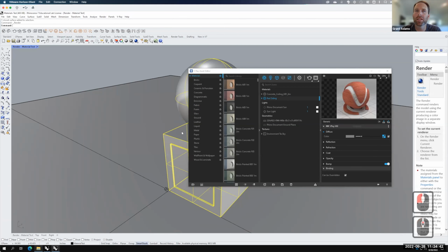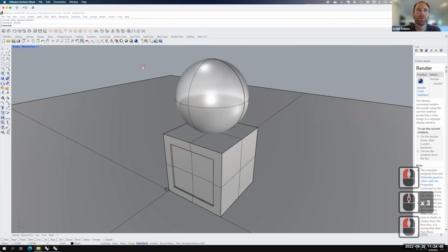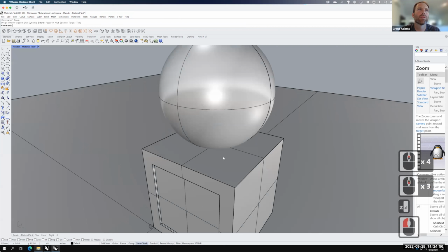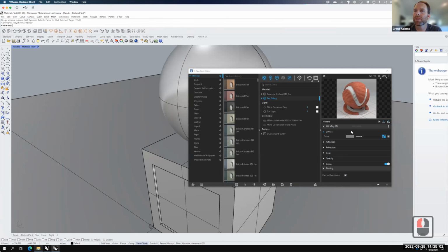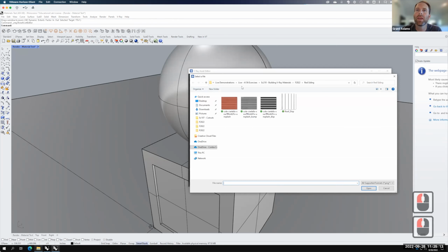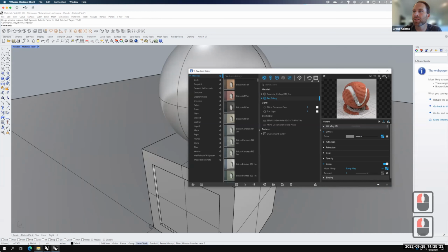And it's probably a little bit easier to see the texture if we zoom in my window here. Why my zoom's not working? I don't know. All right. So let's open back up that V-Ray asset editor. There we go. And under my red siding, I'm now going to look at the bump map. So down here, and I'm looking for that checkerboard again. And this is where I'm going to load in the black and white image that has the texture on it. So we'll go ahead and choose open there. And now I have that black and white high contrast image, and I'm going to start to have some actual texture on it. So let's go ahead and do a render.